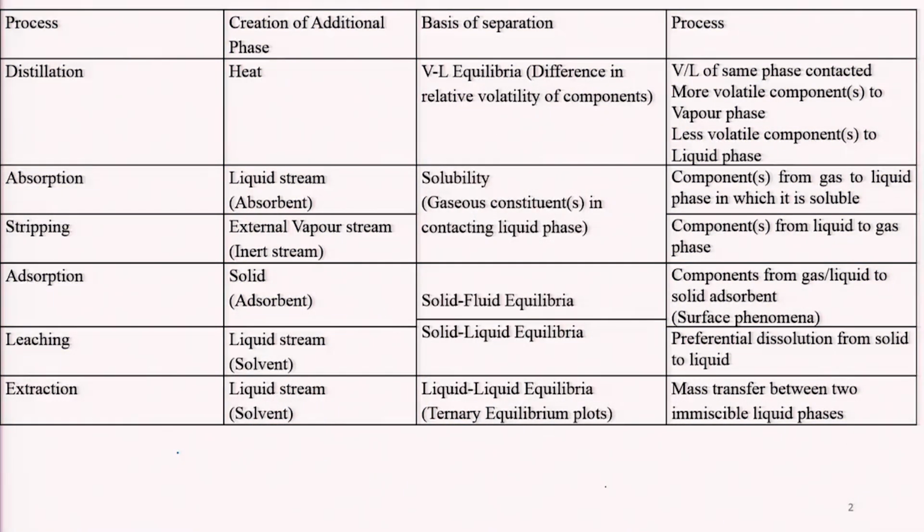Therefore, the basic operations which we had discussed in the last class, and the operations which we will be discussing in much more detail in the subsequent classes, for example distillation, absorption, adsorption, extraction, etc., are all basically interphase mass transfer operations, where the second phase is either created by addition of energy, primarily in the form of heat, or by pressure reduction, or by addition of a second phase.